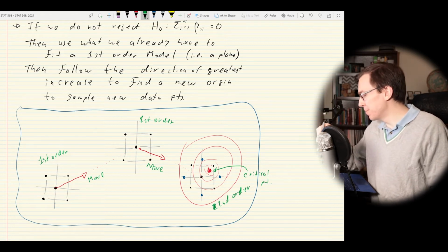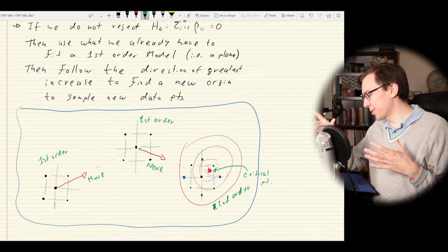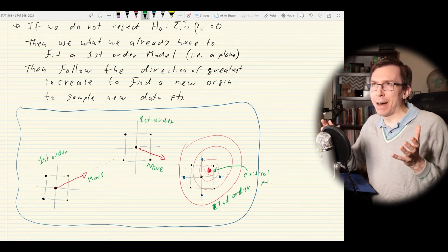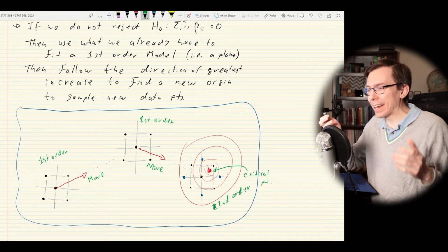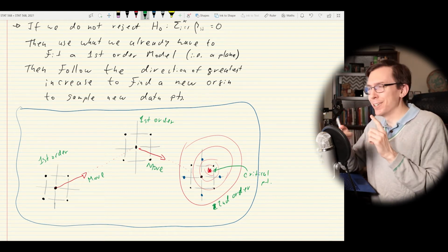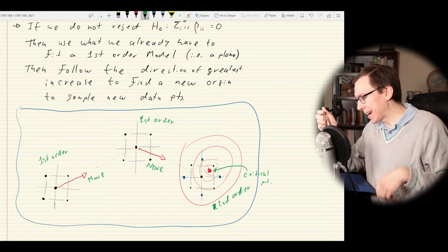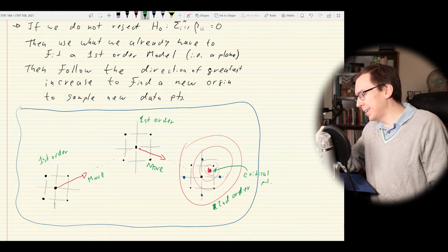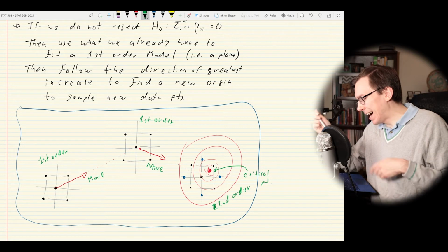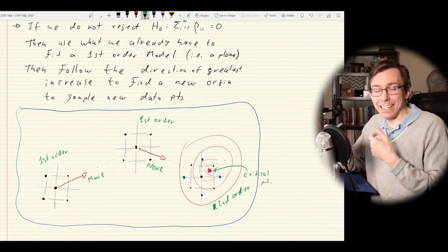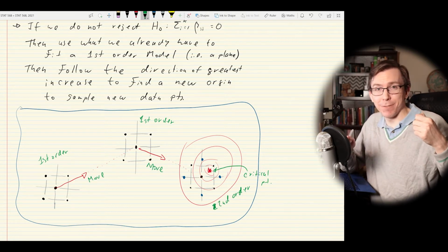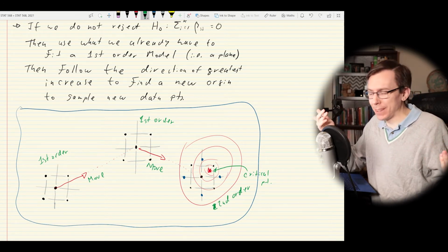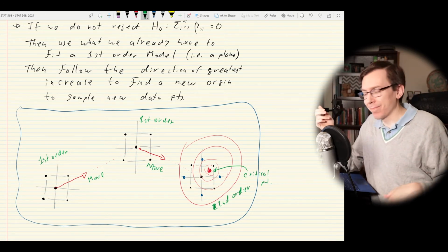We collect all the blue points. We fit our second order surface. Hopefully, it's a parabolic surface that's facing in the right direction and not either a saddle point or going in the wrong direction. And then what we can do is identify the critical point there. And then we say, that red star, that's exactly the temperature and pressure settings we need for our hypothetical machine to give us the most output that we want, right?